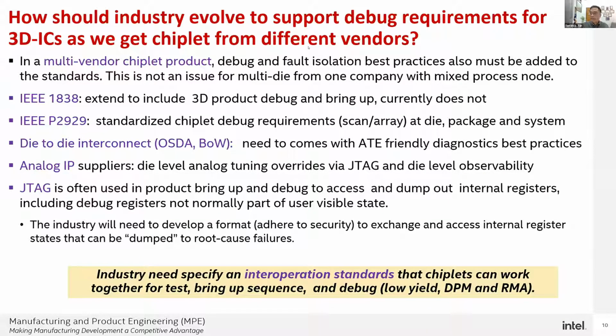Sure. Actually, the P29 standard is quite new. I got to know it recently. It's a standard where we focus on what we call scan and array dump, right? It's not publicly known yet, but you can find out it's run by Dr. Sankaran Menon of Intel. This standard is more of a debug mechanism for scan dump.